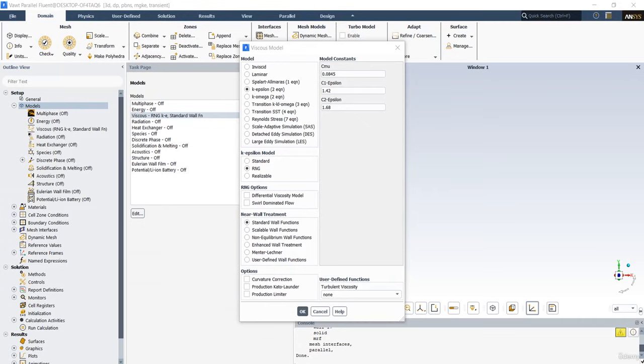Among others, the constant shear and local equilibrium assumptions are the ones that must restrict the universality of the standard wall functions. Accordingly, when the near wall flows are subjected to severe pressure gradients, and when the flows are in strong non-equilibrium, the quality of the predictions is likely to be compromised.